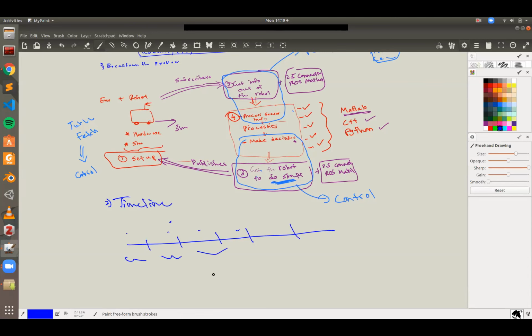Okay, I have a question. Should we set it up using launch files or just rosrun? Also, should we use RViz instead of Gazebo? Okay, so I mean, you can create a launch file. A launch file would just make it easier, right? But it's not that we're going to mark you down because you didn't have a launch file or something like that. As long as your final demonstration works well, that's all that matters.